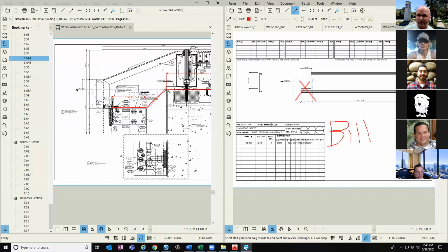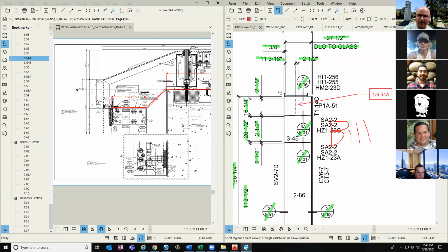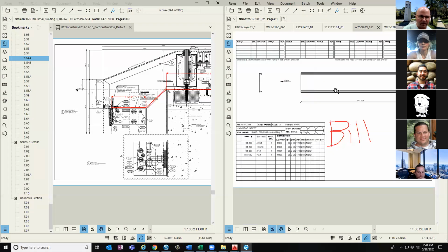So I'm going to check that miter degree. I'll adjust the length as necessary. I'm going to do all the calculations to make this work. But then on the other head member now, in this particular case, I need to do a notch on the one end. And I'll make sure that it's on the correct end, notch the right side. And I'll have to call out specifically that I want this one and only this one to have that notch on it. So I'll recognize what my mark numbers are here.